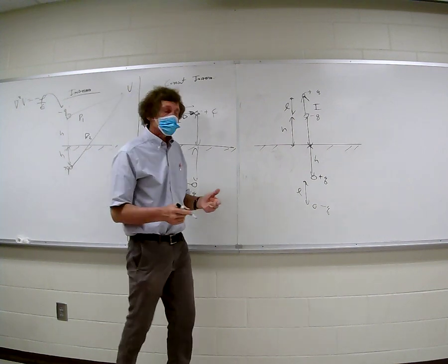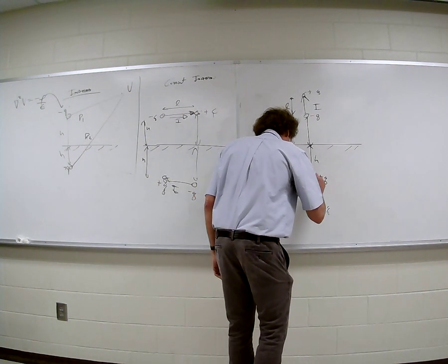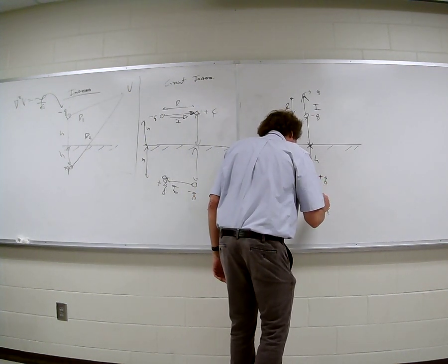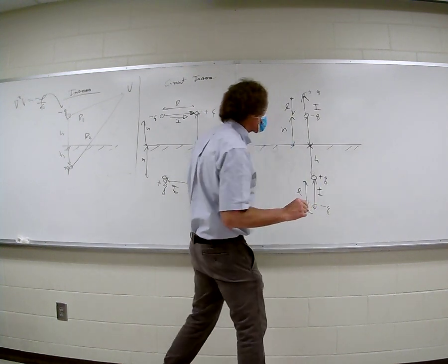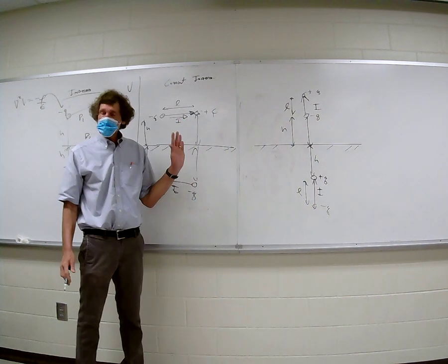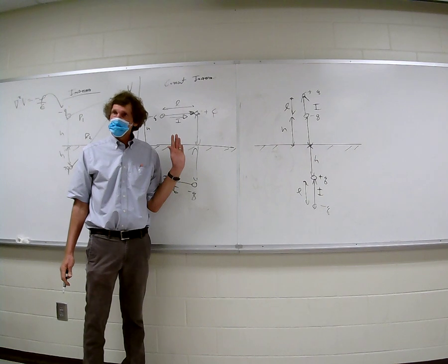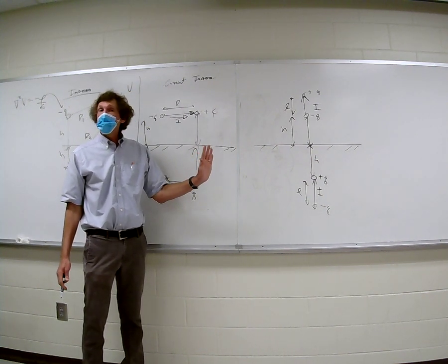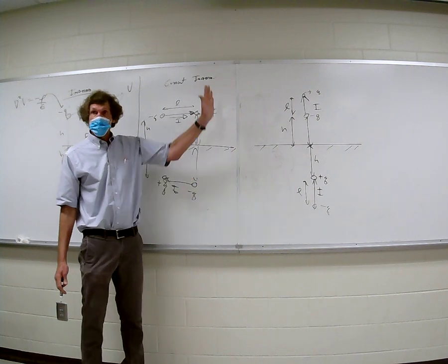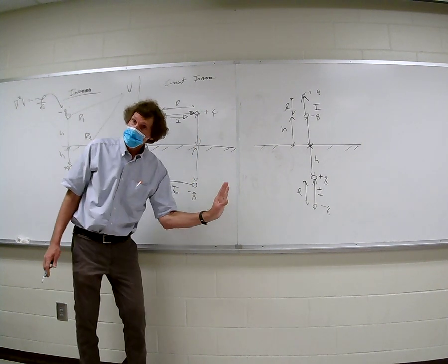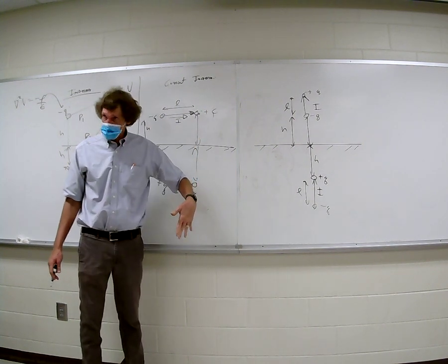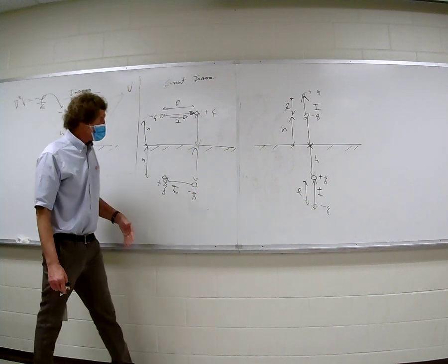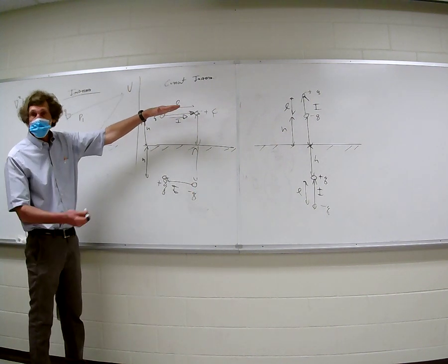Now, you simply show what an actual current would cause that, and the current would be in this direction. The moral of the story is currents in the same direction, vertical currents always image in the same direction. If it's going up, its image is up. If it's going down, its image is down. With me? Currents that are parallel image in opposite directions.